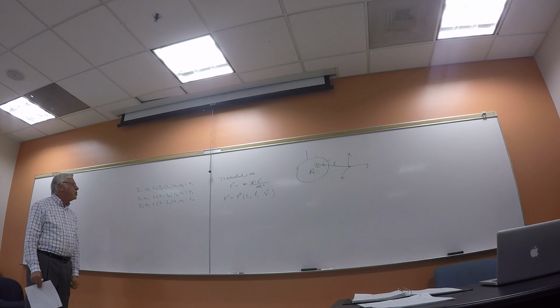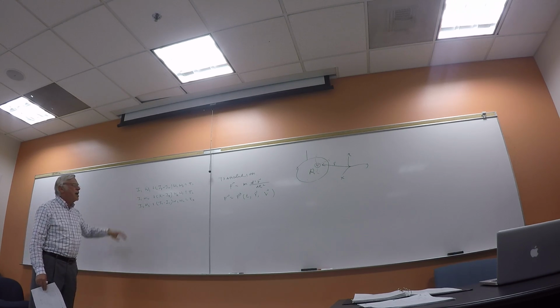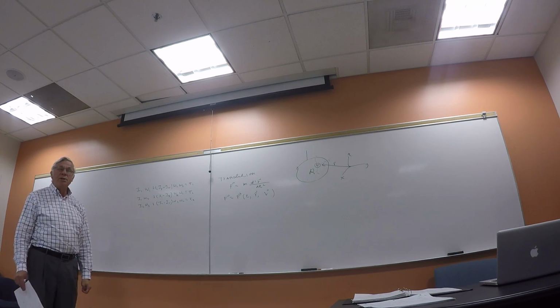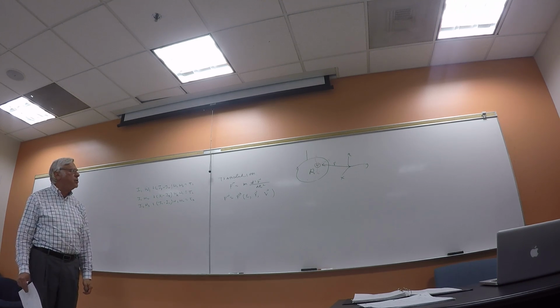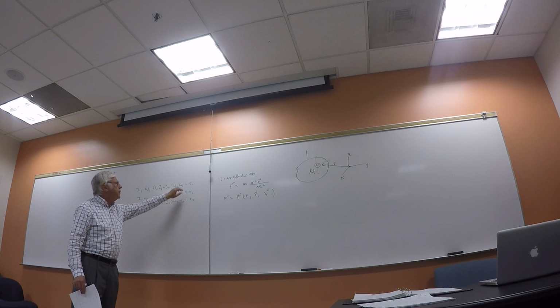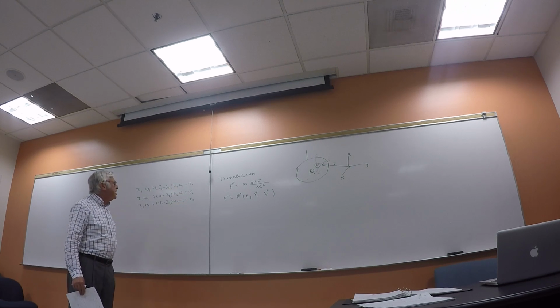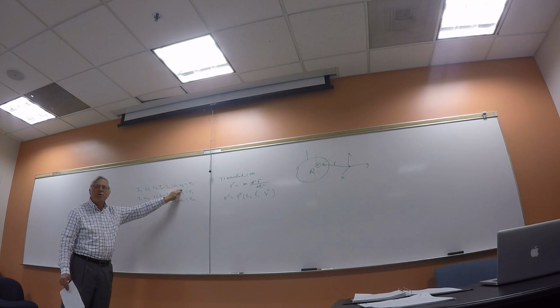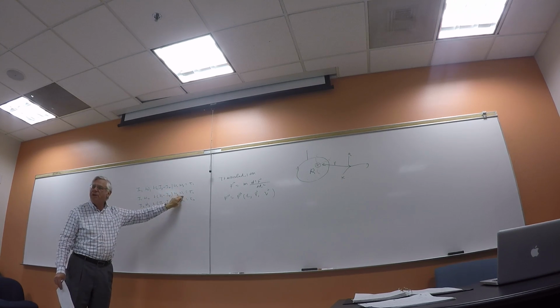But from the mathematical point of view, what I want you to understand is that you have to solve these guys for omega 1, omega 2, and omega 3 as functions of time. Given the initial conditions, of course, omega 1, omega 2, omega 3 at time 0, and you can see, even if these torques were simple, see how it's nonlinear, omega 2, omega 3? It's the product of the dependent variables.